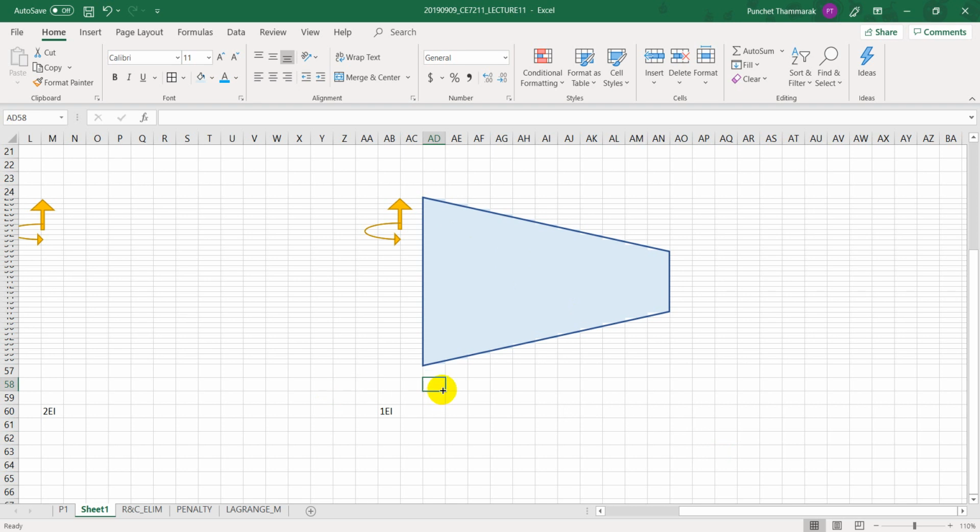Out of these 16 sub-beams, you find the middle point of each sub-beam, and at the middle point, you find the corresponding EI. Then you use that uniform EI to represent your member in that sub-beam, the small beam.